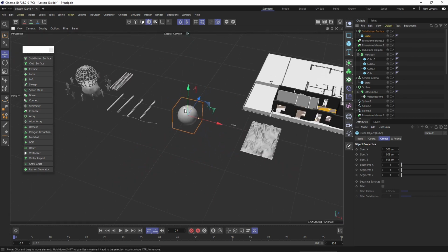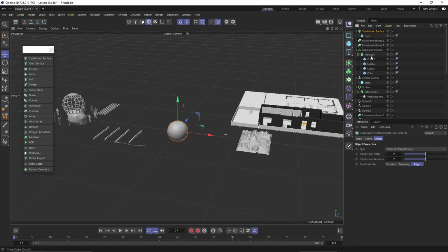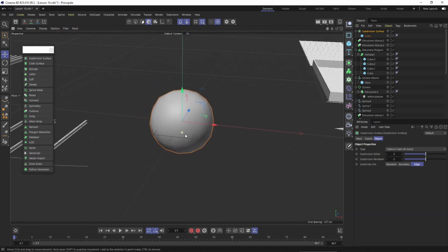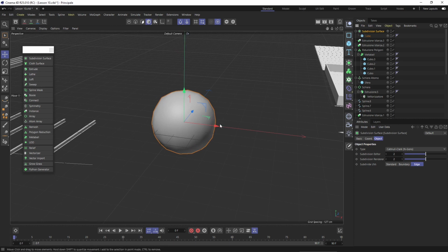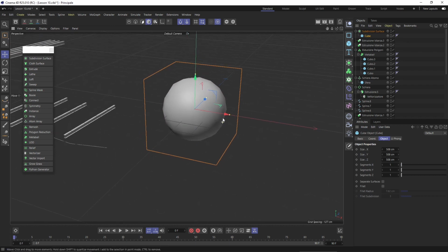Now all the generators work essentially in the same way. You create the generator and you insert the shape or the 3D solid, or multiple solids or shapes, that you want to use with the generator. For example, we already saw the spline mask in a previous video, and we also saw the extrude, lathe, loft and sweep modifiers. So we already know how they work. Essentially they are modifying the original solid, which was the cube or the original element.